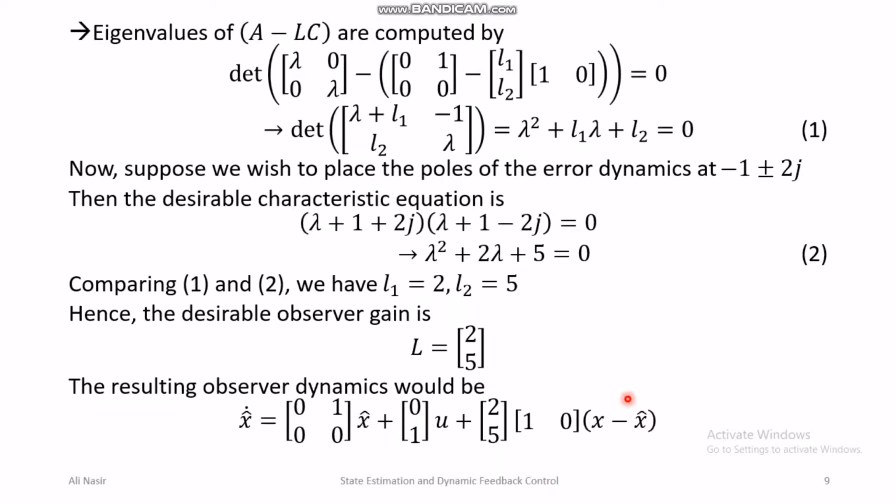in the system. So as far as your project is concerned, there is no additional cost, because in order to implement the controller you already have to have the computational capability in your project. So you can use the same computational capability to implement the observer that you are using to implement the controller. And the advantage is that instead of having full state feedback, we are just measuring state x1 and we don't have to measure the state x2.